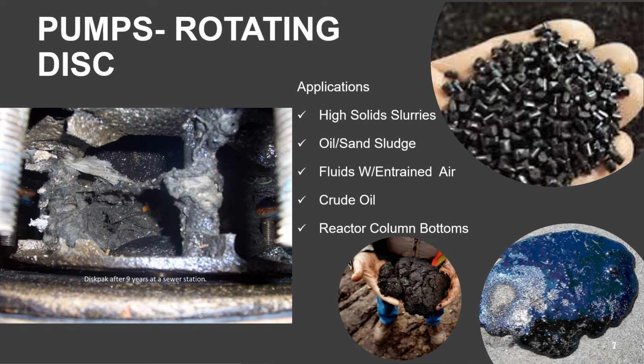The ability to pump ultra shear sensitive products without damage has led to disc pumps being successfully applied in diverse challenging applications, from polymers to crystalline products to latex and oil water separator feeds. The disc pump is also uniquely capable of pumping fluids or slurries with exceedingly high volumes of entrained gas or air, such as foams and crude oil with sand and gases.